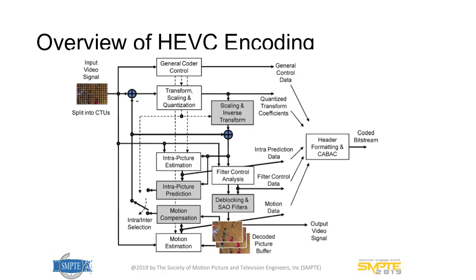So you look at the last block over there called motion compensation. We take a previous frame and try to do either interprediction, which is frame-to-frame prediction, which for video is obviously the highest compression possibility, or intra-prediction, where within the frame we try to predict it.